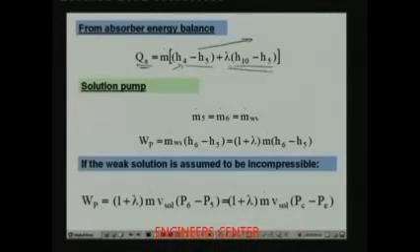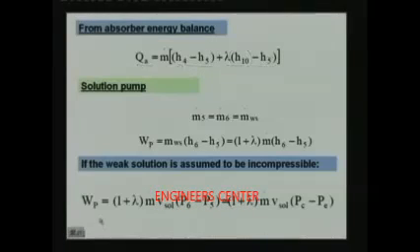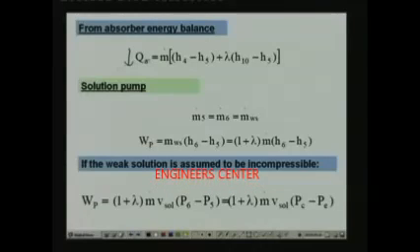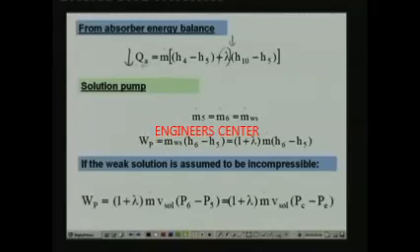Okay, and this accounts for the sensible heat transfer part. What is this thing? This is nothing but the sensible heat to be transferred as the solution at condition 10 is cooled to solution at condition 5. Okay, so you can see that this consists of two terms. Normally from the performance point of view, from the absorber size and all, this should be low. Okay, this parameter has got to be low, because other parameters are decided by other performance related issues like your refrigeration capacity and all. Okay, so you can see that when circulation ratio is low, the heat rejected at the absorber will be low.